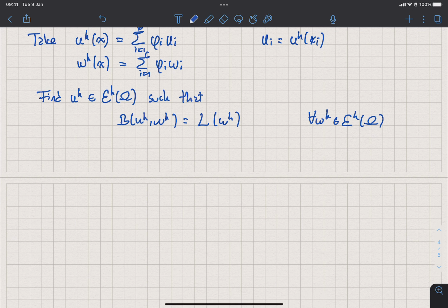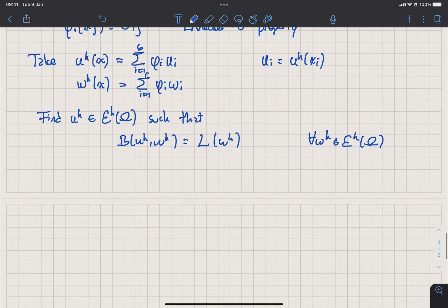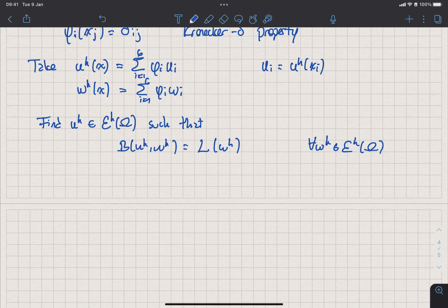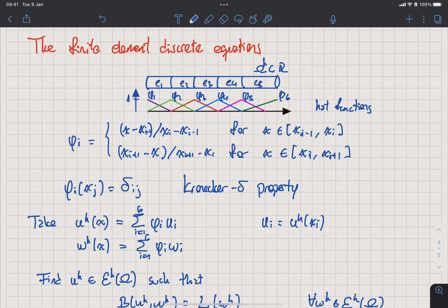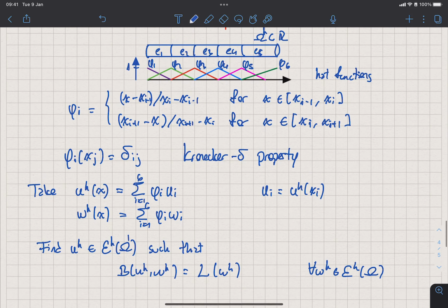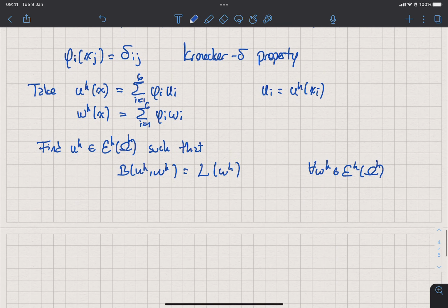And by the way, I didn't put it here, but normally when you have a discretized domain, you also use h. In finite elements, omega and omega_h don't necessarily have to be the same. So omega is your, let's say, your body, right? But omega_h is usually used to denote the discretized version of that body. So normally what we do here, this was going to be omega_h, and here as well omega_h. But in the one-dimensional case, both are equivalent, okay? In 2D, that doesn't happen.